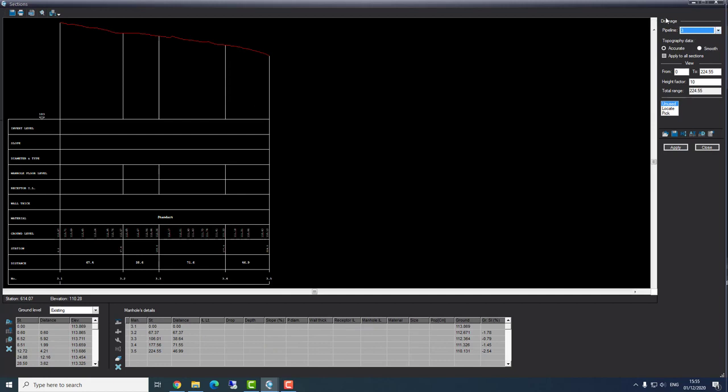I can see right here on the top that the pipeline is drainage. Here the drainage will start with a depth of 1.5 meters. So I'll go to depth, I'll mark all the rows and I'll enter 1.5 meters. Enter. As we saw before, automatically all the invert levels and the slope are calculated. Here in the slope, I want to change it to minus 1.5%. Why minus? Because the pipeline is going down. I'll press enter and I'll press apply and we see what I created.